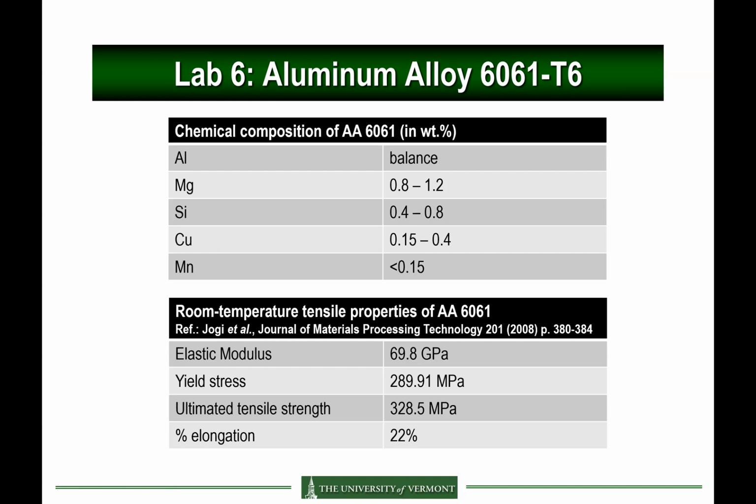So aluminum has a low melting point on the order of 600 degrees C. So it's not considered a high temperature material, but by adding magnesium to it, we can raise this by maybe a few hundred degrees. So for hot parts, or if you have a cover in your jet engines that's made out of aluminum, then the strength of these materials remains relatively high even if you heat them a little bit.